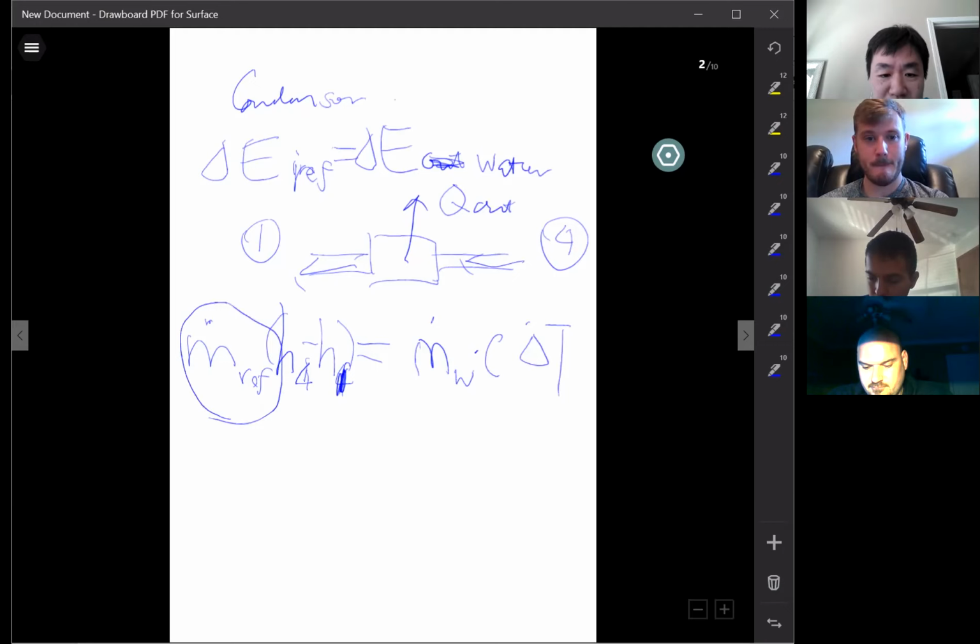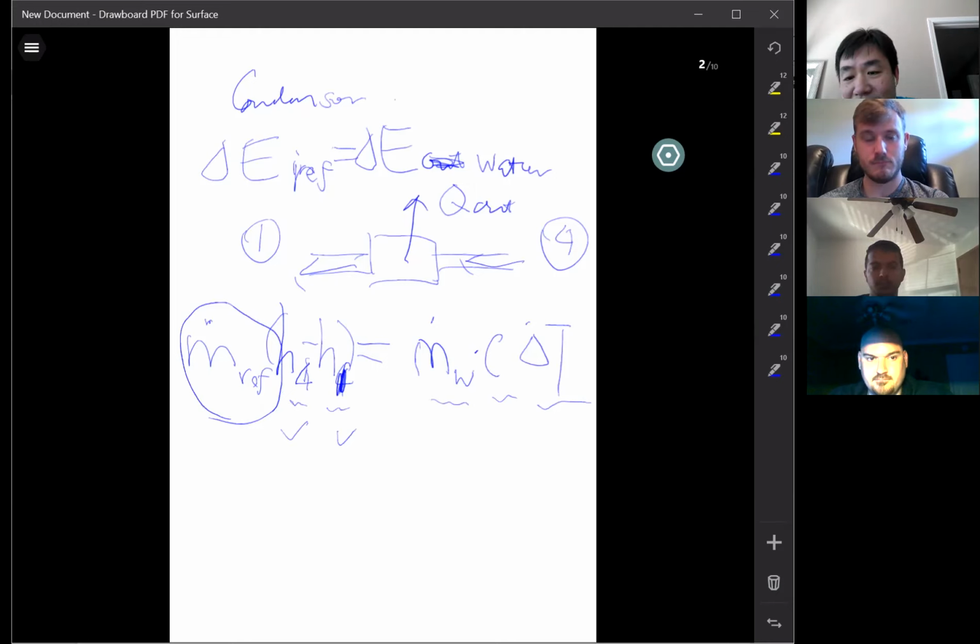okay? So you need to know everything else, measure everything else, or get everything else in order to calculate this mass flow rate of refrigerant. Do you know everything else? You obviously have this, you already did it in the first lab. You need all the H's for the pH diagram. So it should be a piece of cake for you. Now just looking at the table or whatever value, you should be able to find these 2 H's, okay, based on the measurement, temperature and the pressure.